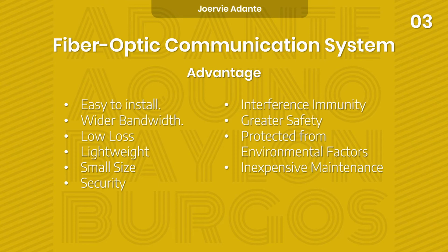Fiber optic cables do not carry electricity and therefore there is no shock hazard. They are also insulators and thus not susceptible to lightning strikes as electrical cables are. They are also safe in corrosive and or explosive environments without danger of sparks. Protection from environmental factors. Resistive to environmental sources since they operate over a large temperature variation.